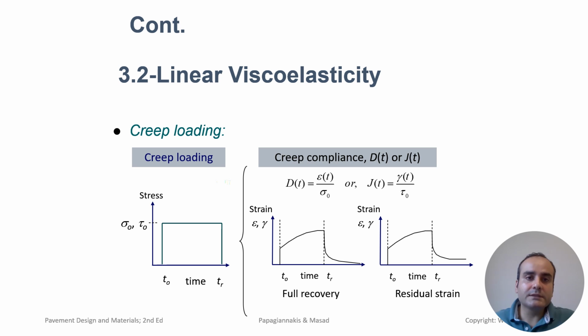There are some key concepts in creep compliance. First, it is a time-dependent deformation. Creep compliance increases over time because the material continues to deform the longer it is under constant stress. Asphalt materials will initially resist deformation, but over time the strain accumulates as the binder flows under the stress.